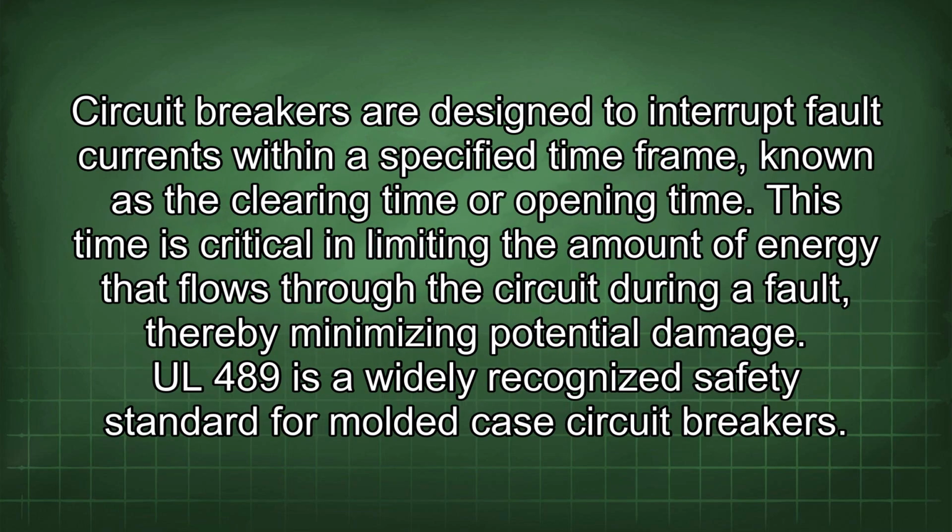Circuit breakers are designed to interrupt fault currents within a specified time frame, known as the clearing time or opening time. This time is critical in limiting the amount of energy that flows through the circuit during a fault, thereby minimizing potential damage. UL 489 is a widely recognized safety standard for molded case circuit breakers.